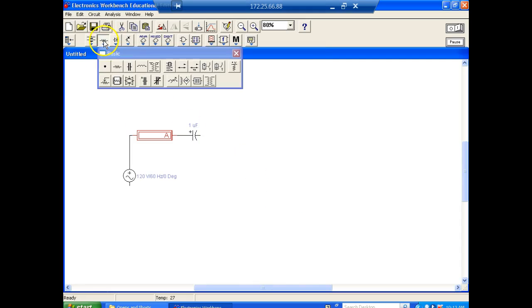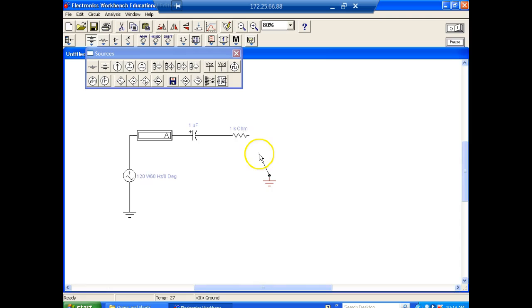The value of the resistor does not change, but the ohm value of the capacitor changes depending on the frequency. And we're not going to show y'all something to get y'all totally confused. So we've got 120 volts. We'll plug this on, see what current we get. But this is at what? This is at 60 hertz.